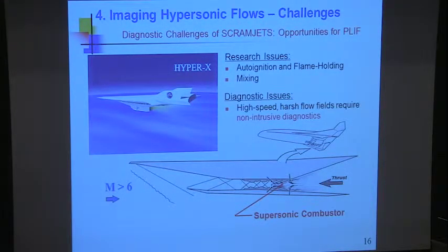Okay, I've also been really interested in scramjets, and this is another opportunity. This was the HyperX concept from some years back. And inside this vehicle is this scramjet concept. Here's some sort of high-speed flight, say Mach greater than 6. Here's the supersonic inlet with some shocks bouncing around it. And then finally, there's a place where you're going to inject and burn fuel. In this scramjet, the rule of thumb is you have to mix and burn the fuel in 1 millisecond.